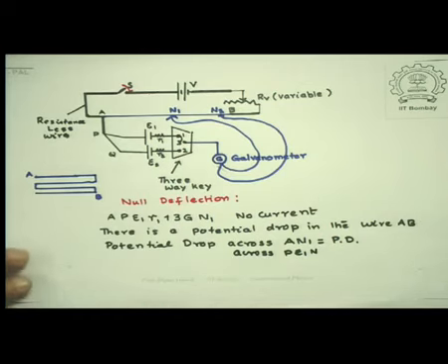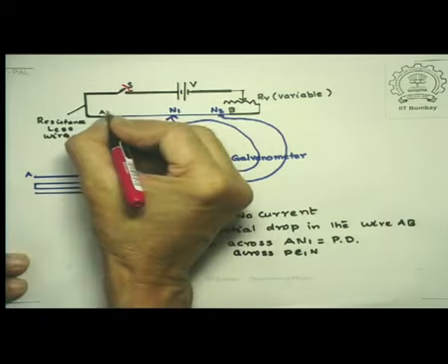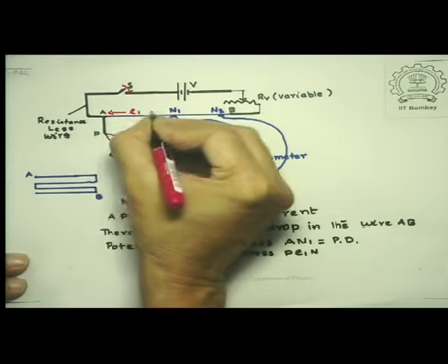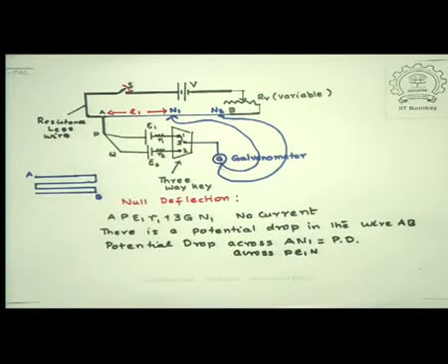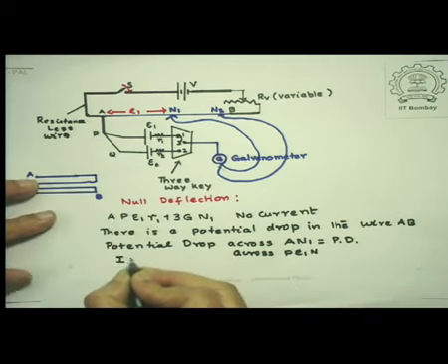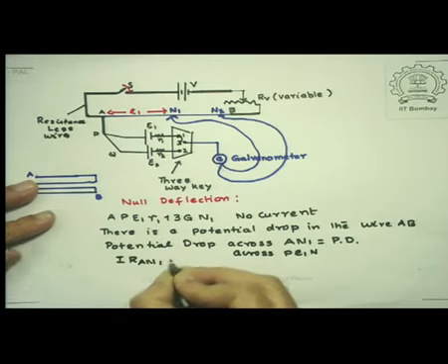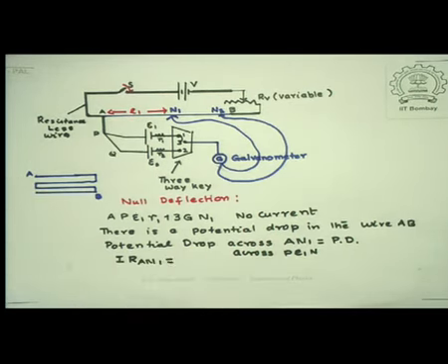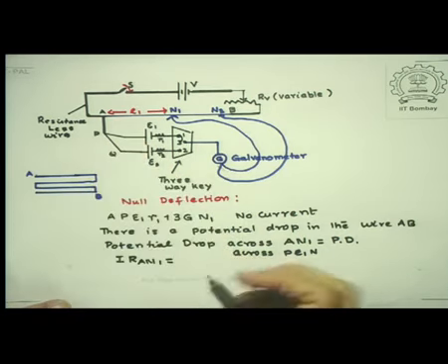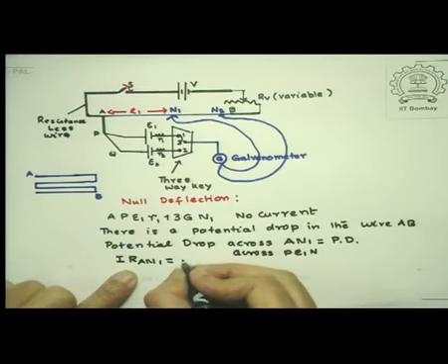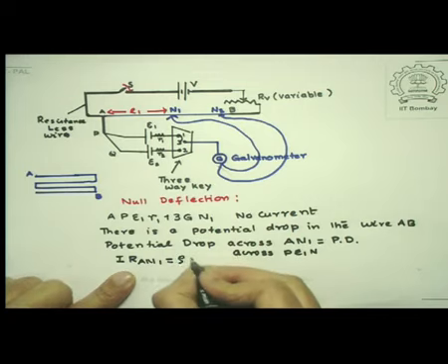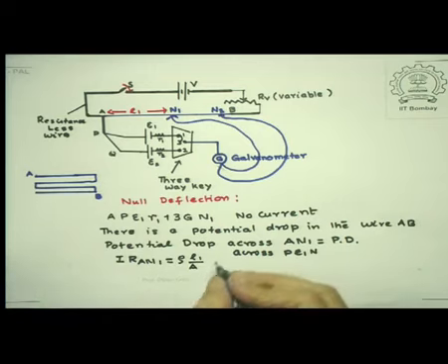Now, suppose the length for which we obtain the null deflection is given by L1. Then what we find is this, I times the resistance of the section A N1 is equal to E1, but how much is this? This is equal to rho L1 divided by A, and that's equal to E1.